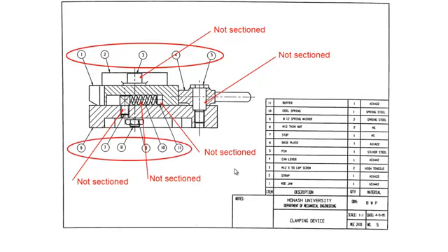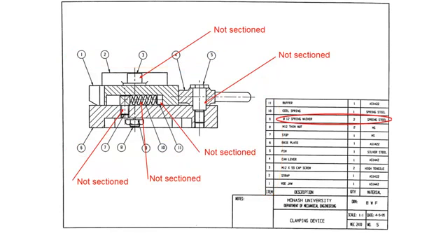We also have our parts list, and we have ordered it starting at 1 at the bottom here, then moving up to number 11 here, which is our buffer. If we look at one of our parts, we've got enough detail here. It's a diameter 12 spring washer made of spring steel. We need 2 of them. There's enough information in that description to go out and purchase one of those. And the same goes here for our M12 thin nut made out of mild steel. We need 2 of those. So once again, there's enough information provided in our parts list to purchase these parts.